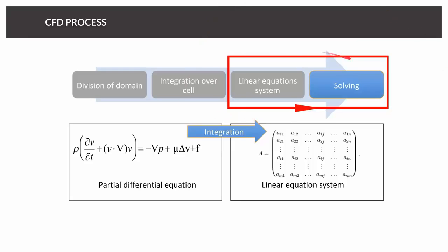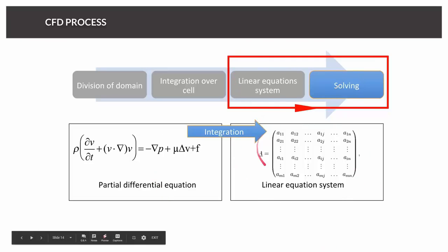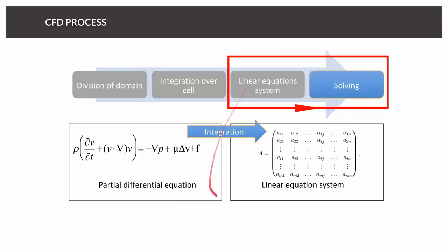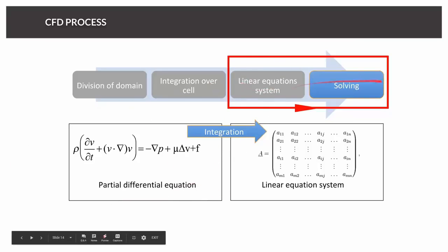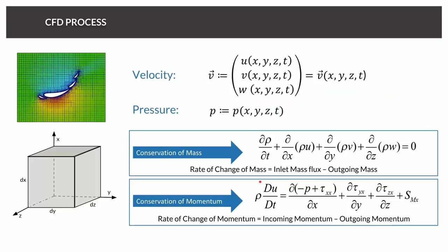And this is what most of you know as CFD, because this is a process of iteration. So we will start with an initial solution. Then we can calculate the residuals, the error, and based on that we will use other values for our degrees of freedom and calculate it again. And this is like an iterative, recursive process. And in the end of the day, this allows us to represent our flow phenomena. And yeah, this is basically the idea of CFD.